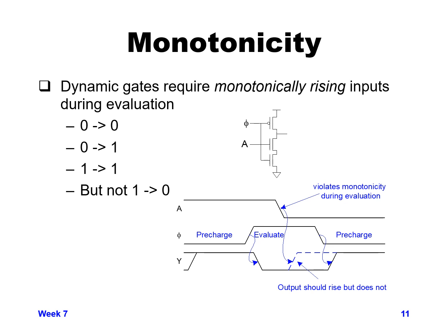And so we have a new timing rule here. If our input is 0 and wants to stay 0, that's fine. If our input is 0 and wants to go from 0 to 1 during evaluate, that's fine. If the input is 1 and wants to stay 1 during evaluate, that's fine.